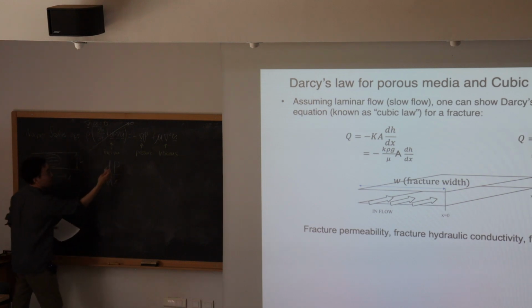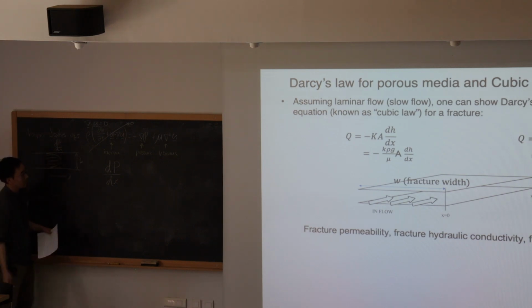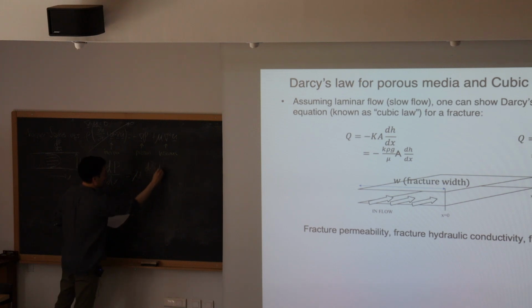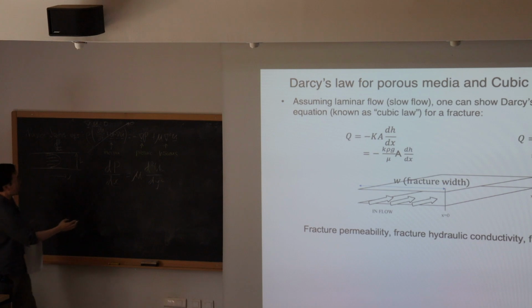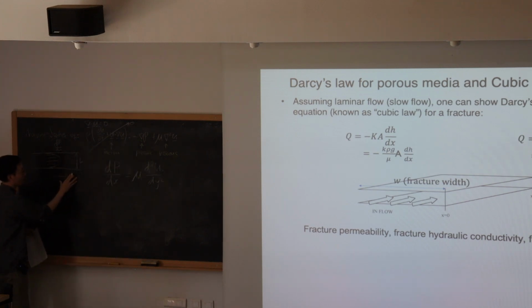dP/dx is the pressure gradient, which is the driving force. Okay, so it's the x-directional pressure gradient that's driving the flow. And that balances the viscous force due to velocity gradient, right? Which is this term here. So it's simply mu times d squared ux over dy squared. Okay? So I simply wrote down this Navier-Stokes equation for the no inertia case in this system, right?